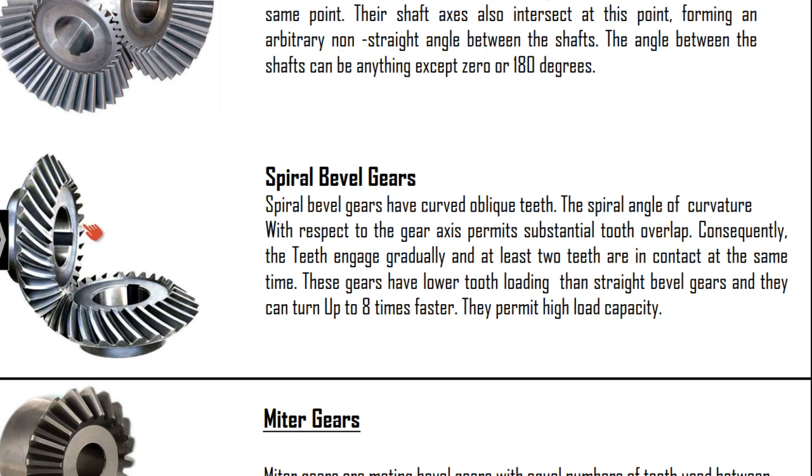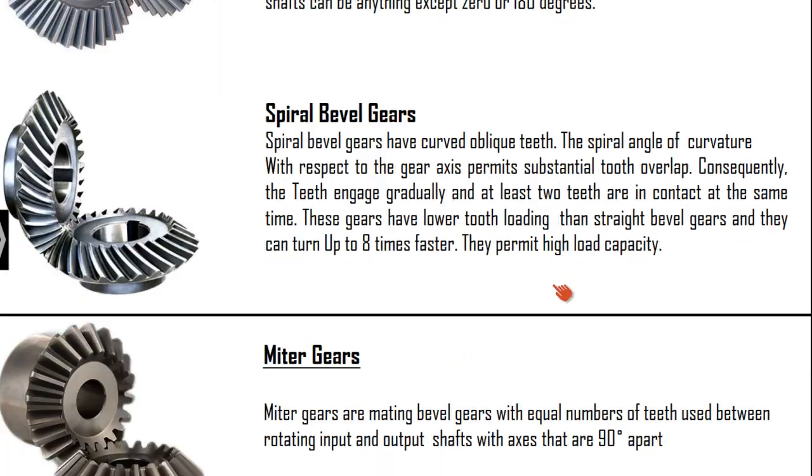So, usually when it comes to higher loading applications or even higher speed applications, we will prefer the spiral bevel gear over the straight bevel gear. These are some of the facts.